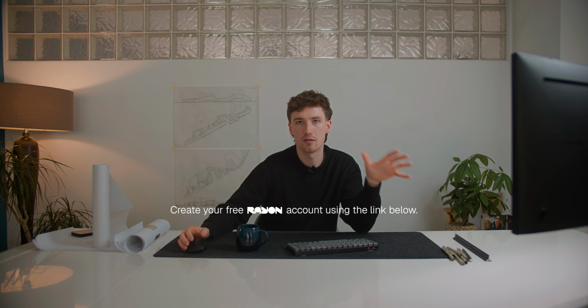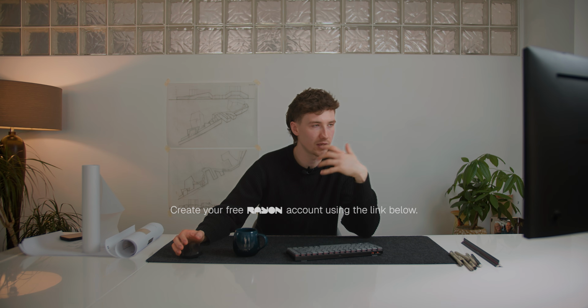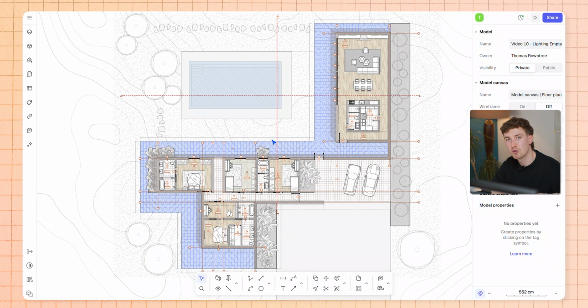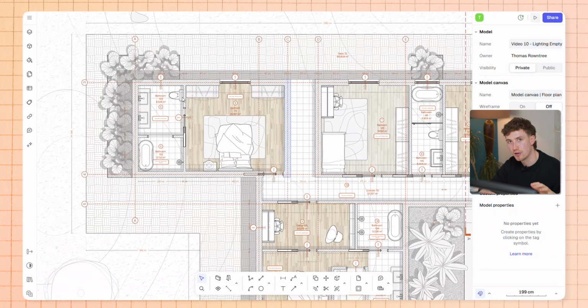Let's start with the lighting layout. A good lighting plan communicates fixtures, locations, lighting functions, and sockets and circuits. And from an architect's perspective, we want to make sure the lighting locations work and coordinate with the layouts. So this floor plan has quite a logical and clear grid structure, and so we want to make sure the lighting plan follows suit and follows that structure.